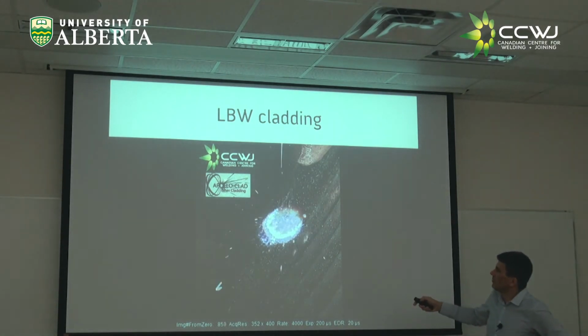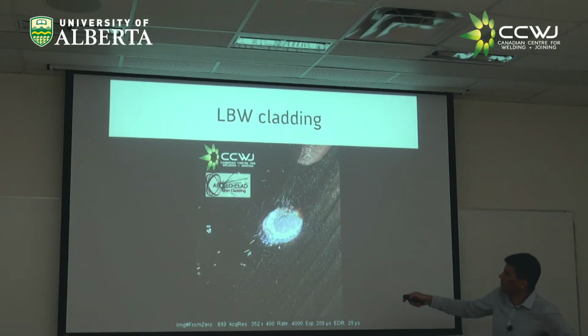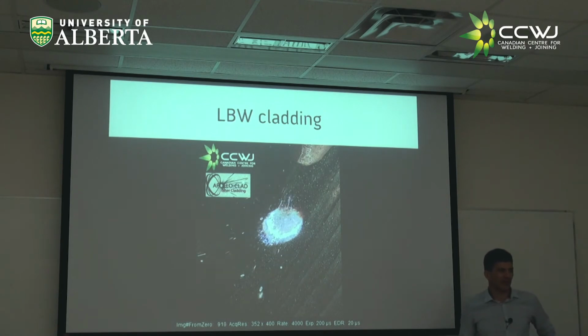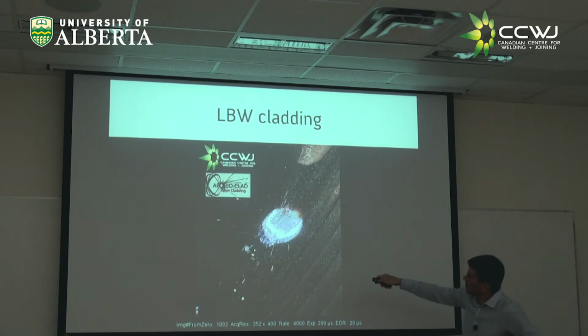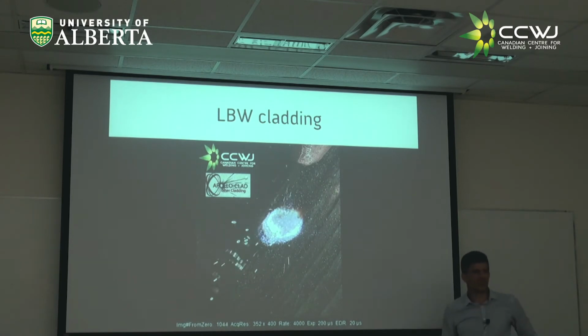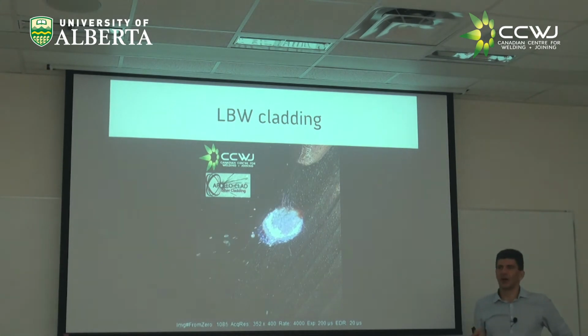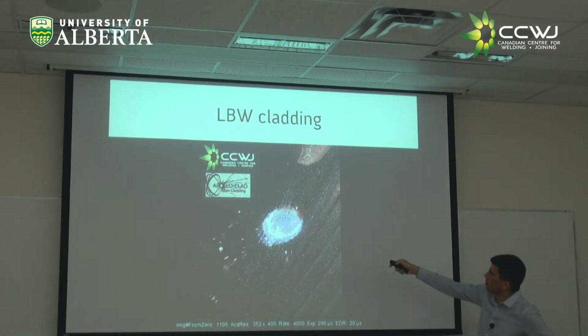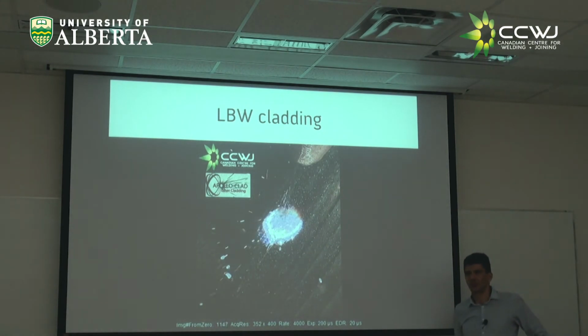Now look at this. Here you see those balls? That's spatter, right? That's metal that is lost. But something that worries me more than the spatter, see all these other things, the powders that never melted, and they're bouncing off the surface? Isn't that crazy? That's money lost. You shoot your powders straight on the weld pool. They should stick, but they don't.